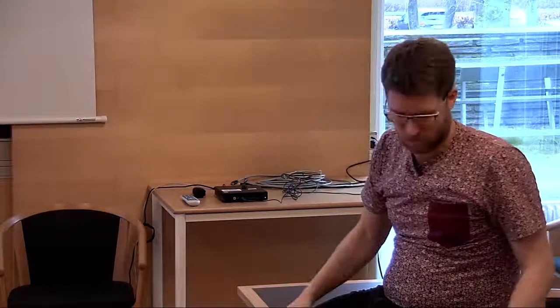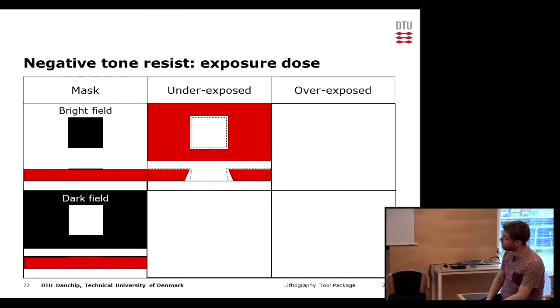And then the last question is, what happens then to the sidewall angle? Well, the entire thing is weaker, so the angle should be more pronounced. Let's hope that's the case. Yep. So the assumptions were correct. We get a bigger hole, we get possibly a thinner film, and we get a larger angle. Yeah?